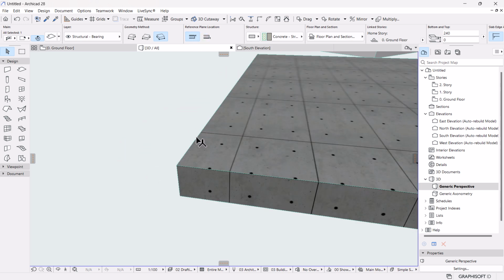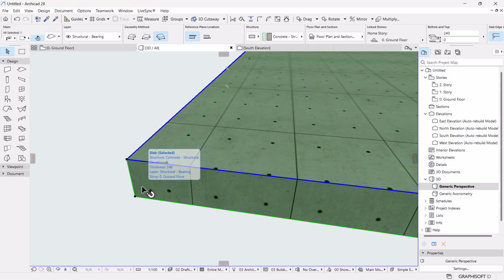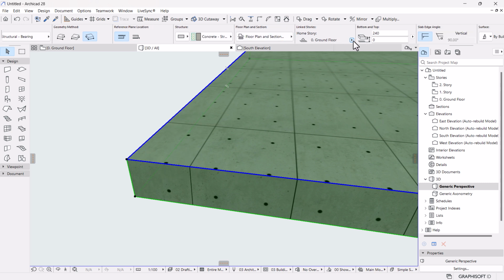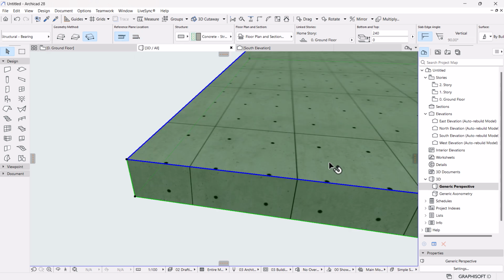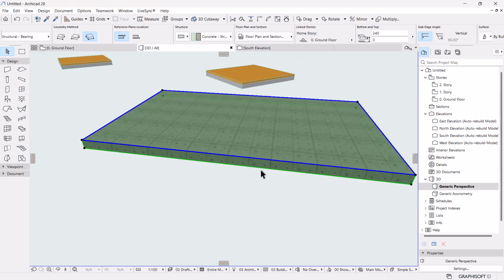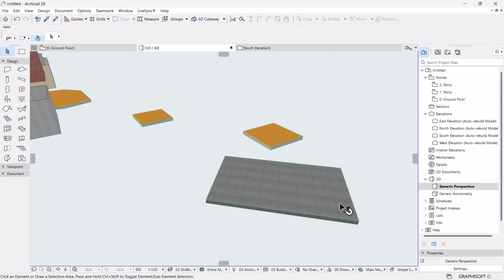So I'll give you the ideal situation. For example, let's key this in to ground, right? And then the level should be what? 0, because maybe your floor finish is at 240, so that means you can't have it at the bottom. If it's like this, that means this is above floor finish. So the top of your floor is going to be above floor finish. It's going to be a step. I think the ideal situation will be to reference it at the top like that. It depends either way, with your standards and your design. Okay.